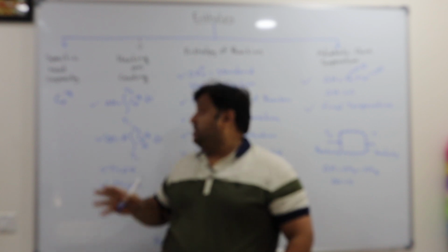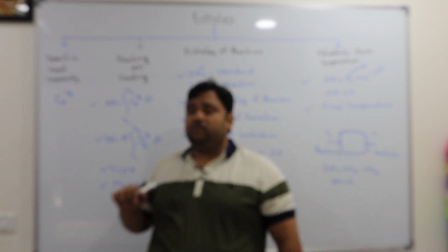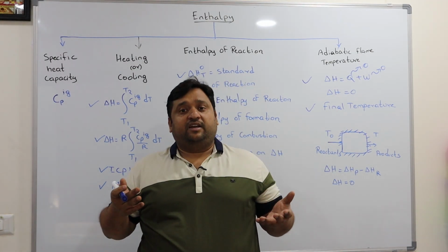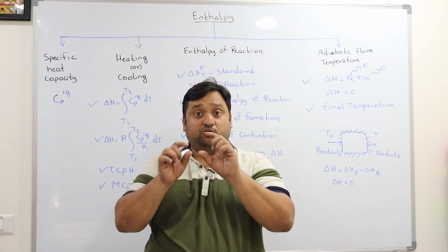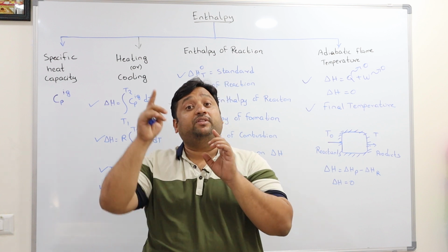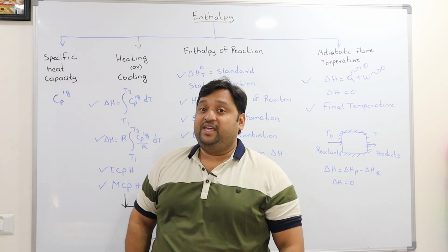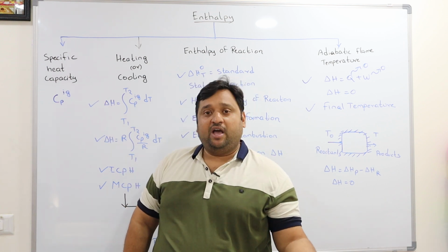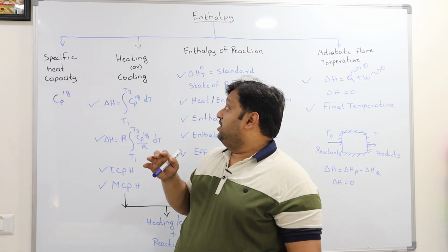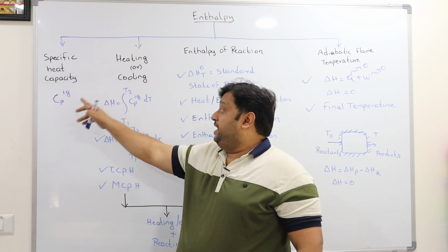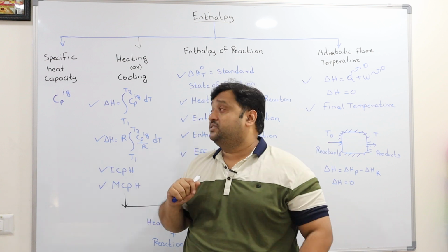If you refer to it, how to estimate the heat capacity is given. That means if you know the constants like specific heat capacity constants A, B, C, D. These are the 4 constants associated with every gas. If you know the A, B, C, D of any particular gas, you are able to estimate the CP, and liquids are also available. So this is how we can estimate the CP. So the second thing, because you need the idea of CP to estimate the enthalpy, energy contents.